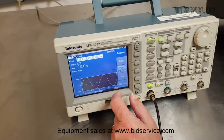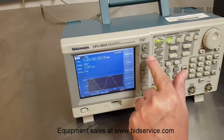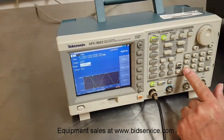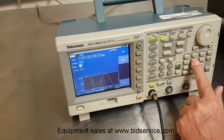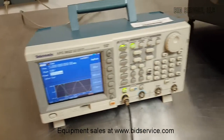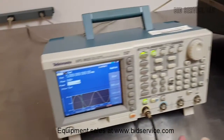To change the amplitude, I'm going to go back to the top menu. I'm going to go to amplitude menu, amplitude again. Here I am. I'm going to change this to 1 volt. Actually, I'll change it to half a volt. So I'll just hit 0.5. And you can see that our amplitude has decreased proportionately, and so that channel is working.